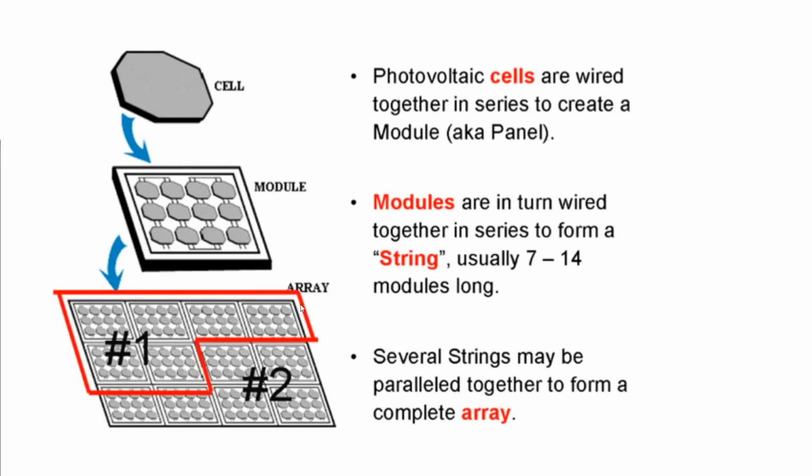With inverters, I guess understanding the jargon is going to really help you. We talked about earlier that a solar cell or a solar panel is actually referred to as a solar module. A series of modules on a circuit is called a string. This is just a jargon term, but a DC circuit is referred to as a string. So when you have a bunch of modules all plugged into each other, positive, negative, positive, negative, positive, negative, that's one string of modules. And if there's another circuit of modules wired right next to it, that's another string of modules. And so a multiple circuit solar array would have multiple strings of DC circuits.